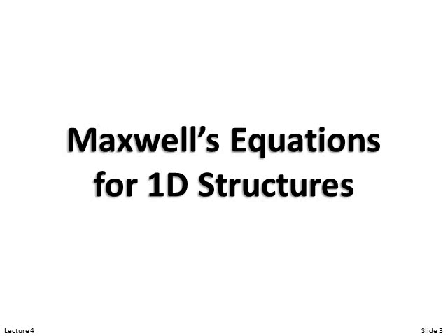During the first lecture, the big thing was preparing Maxwell's equations for solving through a numerical method, and we did several things. We Fourier transformed from the time domain to the frequency domain. The big thing that happened there was that the epsilon times E and the mu times H, which were convolutions in the time domain, become just simple multiplications in the frequency domain. So that really simplified. Then we took our constitutive relations and substituted those into Maxwell's equations, and when we did that, we eliminated the D and B fields, so we're left only with E and H.